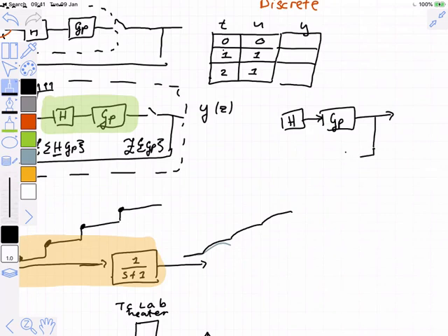And I may accentuate the fact that I'm doing a sampled measurement by putting that sampler in that feedback loop position, where I normally would have GM, a measurement transfer function. Maybe you could also include some dead time here, but you could have any kind of GM. And remember, that would be a discrete transfer function going back. Now we have our controller.